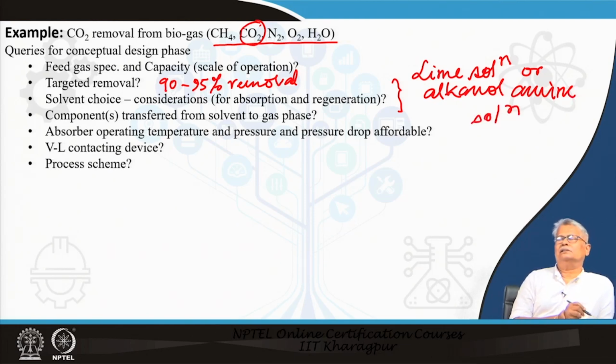Typically 10% diethanolamine is a very good option for removing carbon dioxide. Now, we have to think about the components that may get transferred from the gas. Whether we are using a lime solution or an alkanolamine solution, there will be some transfer of water going from the liquid to the gas phase.